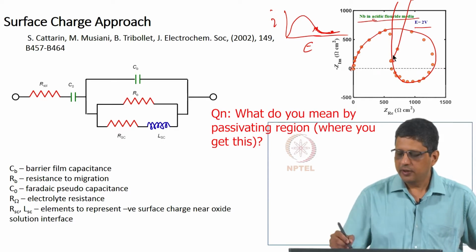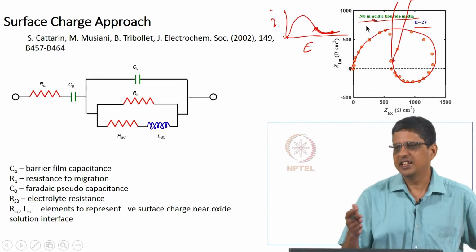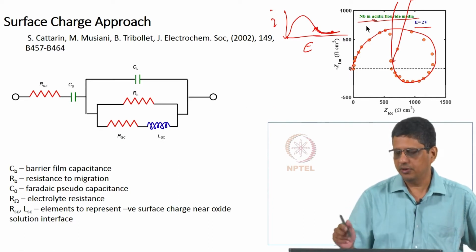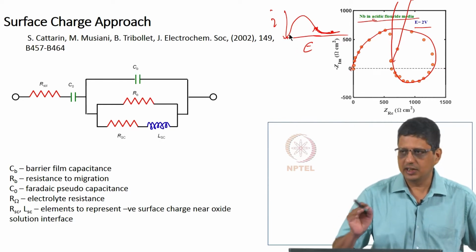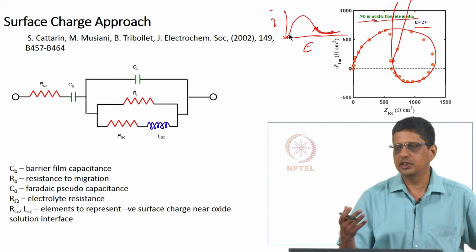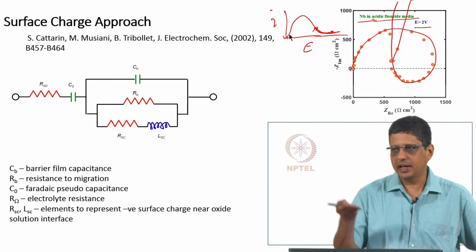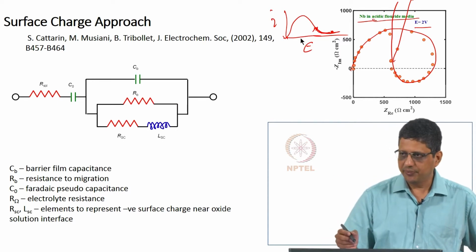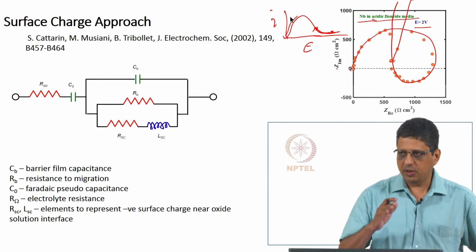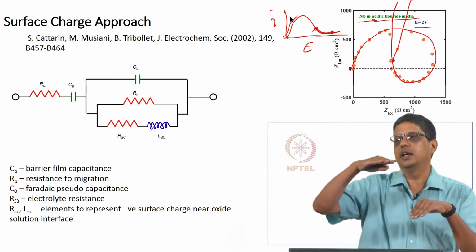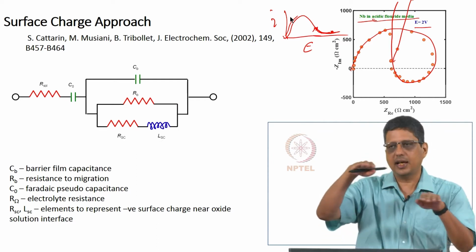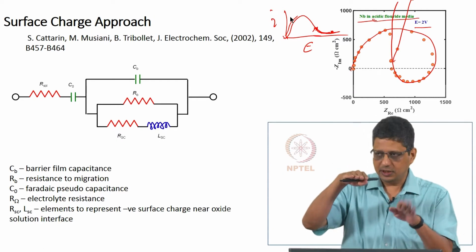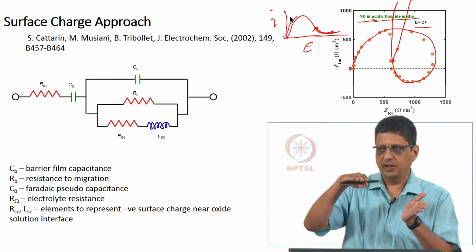When you put niobium in acidic fluoride medium, meaning HF based liquid, it can be with buffer, without buffer, it will dissolve. When you do not apply any potential, it will dissolve, depending on the concentration, at a higher rate or lower rate. If I give positive potential, the dissolution rate will increase up to some level, the current will increase up to some level. Oxide formation rate will increase. Let us say that the net rate of dissolution in this particular solution is at this level. I am just going to draw in the air. Metal converts to oxide, oxide is dissolving into the liquid.